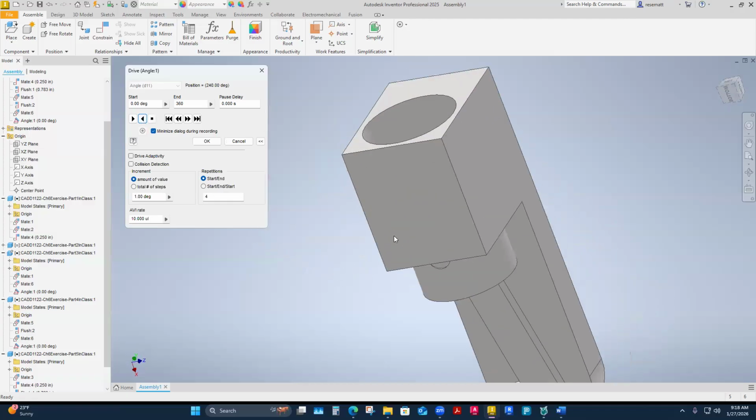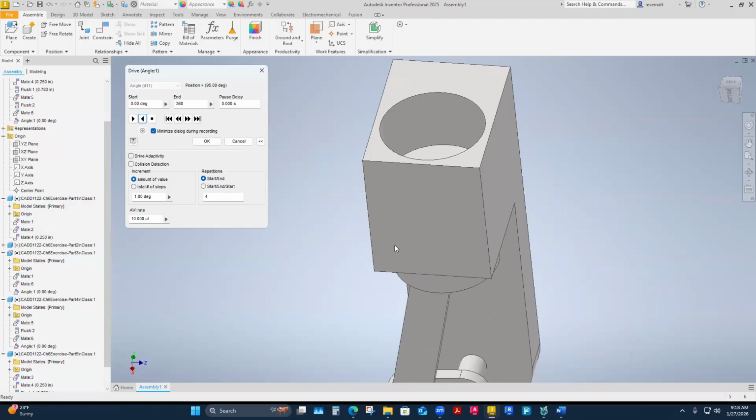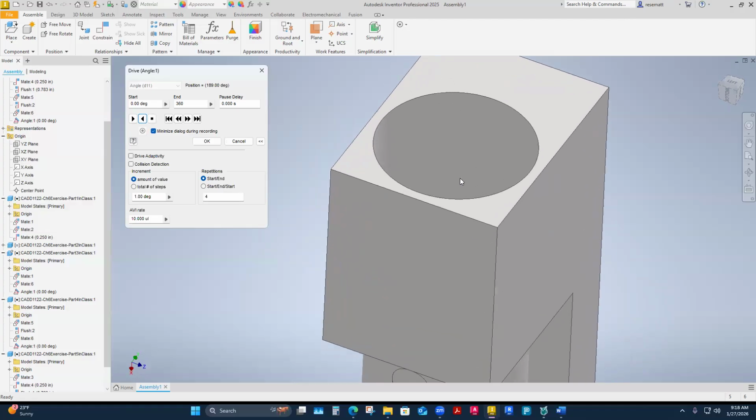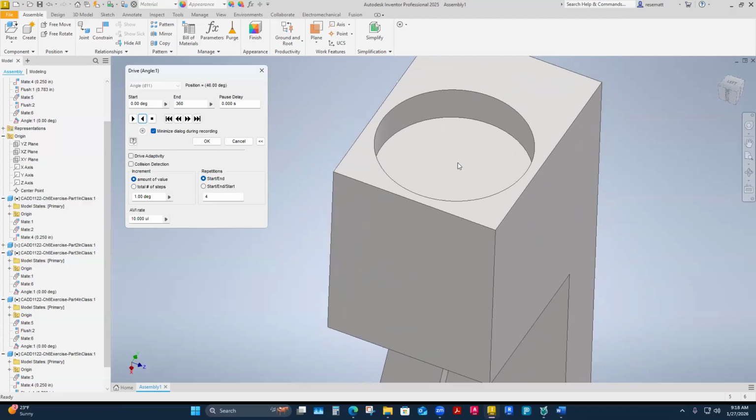Yeah, so this is your car engine, right? This is just like your crankshaft does this. What you're doing is you're injecting fuel and air into this cylinder here, and this is where the piston compresses that fuel air mix, and then a spark plug initiates a spark that ignites that fuel air mixture in that piston and it causes a controlled explosion, boom, and it forces that piston back down.